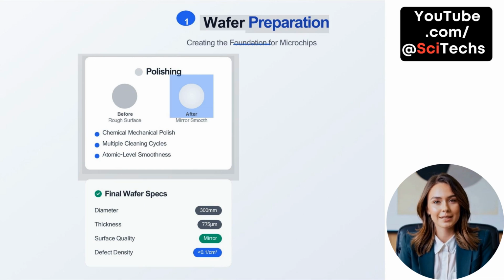Wafer preparation, polishing. After slicing, the silicon wafers have a rough surface that must be refined to enable high-precision microchip fabrication. This is where polishing comes in. Using a process called chemical mechanical polish, or CMP, the wafer surface is smoothed to near perfection. CMP combines mechanical abrasion with chemical slurry to remove surface irregularities without damaging the crystal structure.